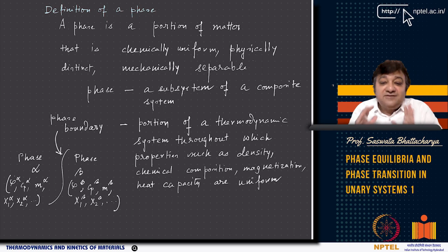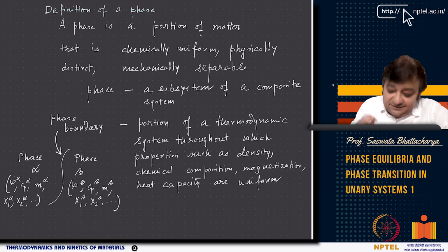So these should have physically and chemically distinct properties, right? A phase has its own composition, for example. That is exactly what I am talking about. And if there are two phases, say in a microstructure in a material, you often see these internal structures under a microscope. In these internal structures, you see different types of contrast, and these contrasts are often identified as phases. When you see the contrast, the main thing that distinguishes these two phases is the phase boundary or the interface between the phases, right?